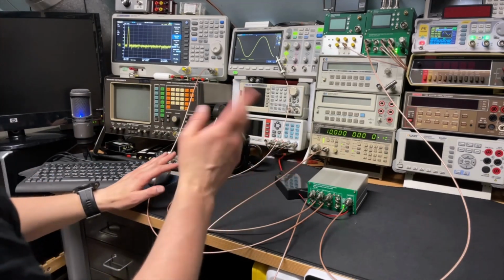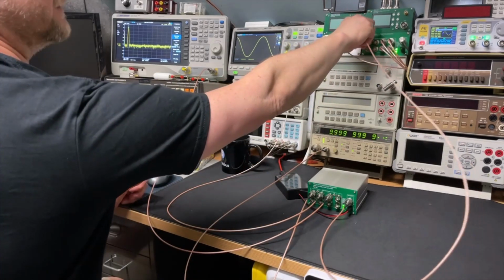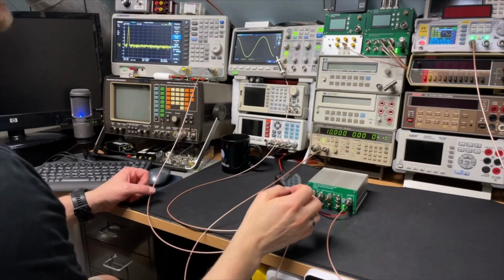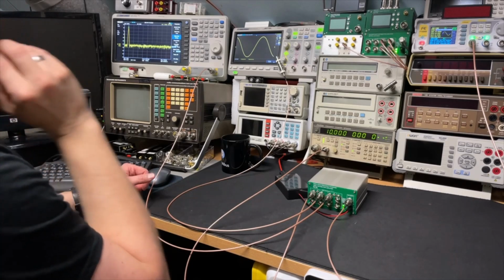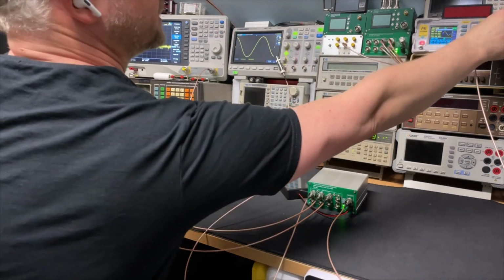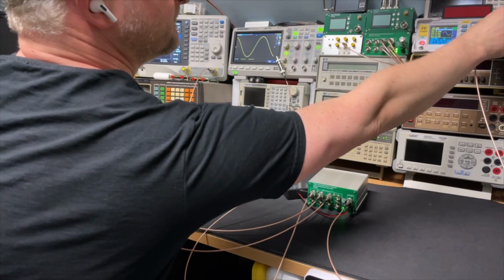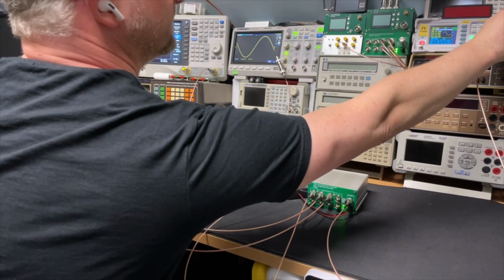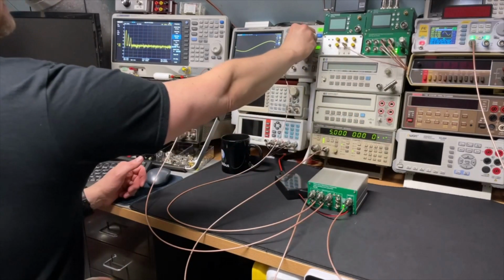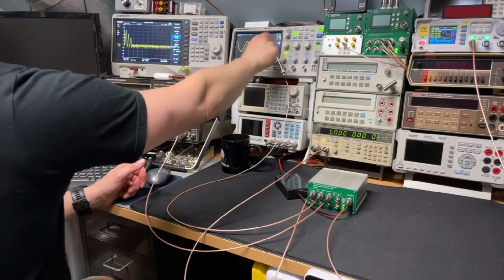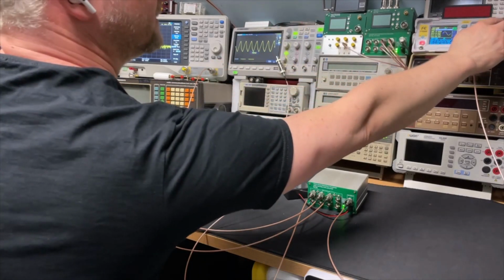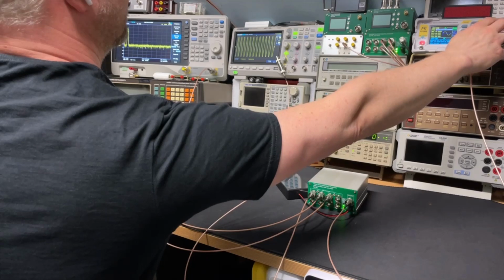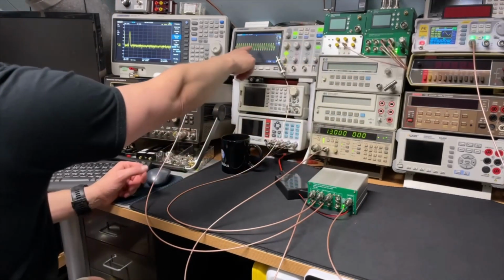So why would you not always buy this one? Well, it depends exactly what you need it for, because now I'm inputting 10 megahertz, and that is perfect. But what if we put now 9? Oh, what if we do 9 or 8? And you see that now the signal is a lot lower. That is because of the bandpass. It will not pass the lower frequencies, and the same is for the higher frequencies, because that is exactly what it needs to do.